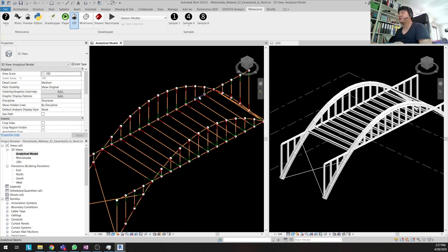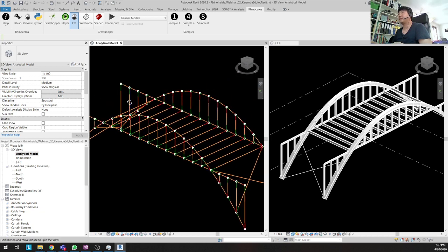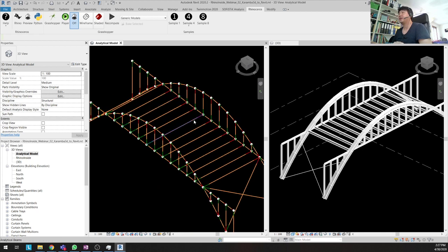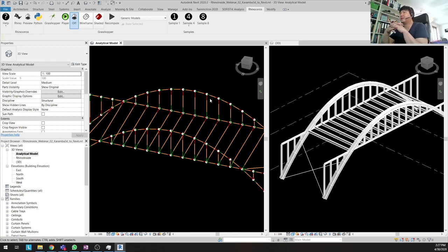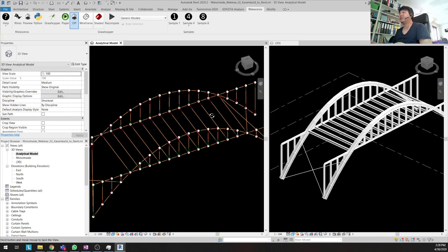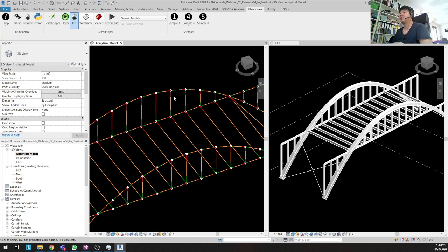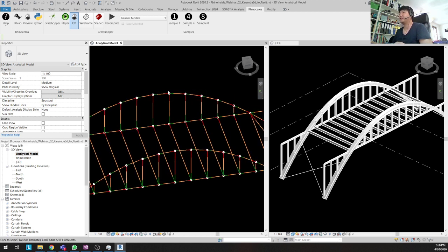Then we can do extra calculations from those software packages, and most of them support a bi-directional link between Revit and third-party software. So recalculated members from extra static software we can bring back to Revit. Then the bi-directional function will automatically convert the existing members by recognizing the GUID from Revit.